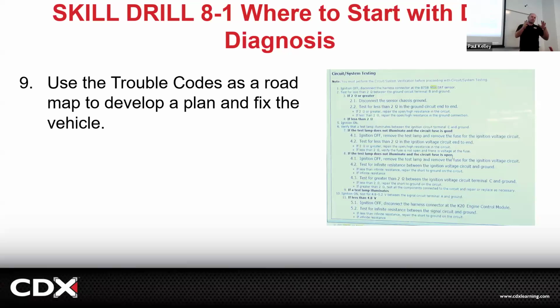So we might move on to compression. So let's just say, is there spark? Yes, we go on to compression. Next step, perform compression test. Is the compression within spec? Yes or no? What do you do? Perform the stupid compression test. Was it in spec? Let's say no.